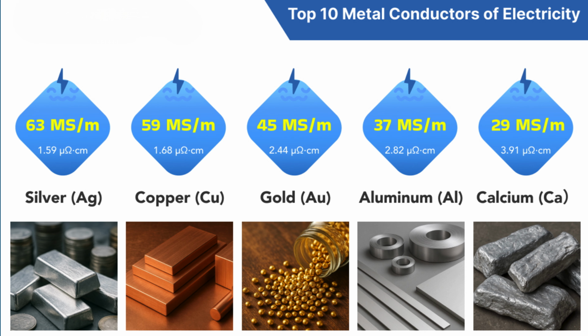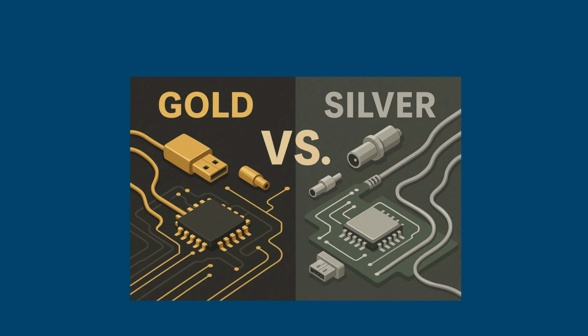Metal back electrodes. Noble metals such as gold and silver are widely used due to their excellent conductivity and favorable work functions. Gold provides optimal efficiency and stability, while silver offers a lower-cost alternative, particularly in inverted device structures. To reduce cost and improve stability, alternative metals, including aluminum, copper, nickel, molybdenum, and tungsten, have been investigated.